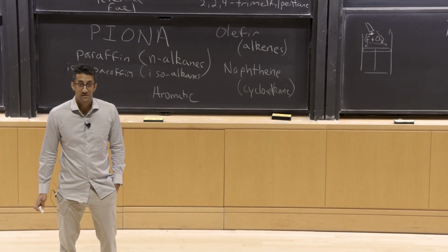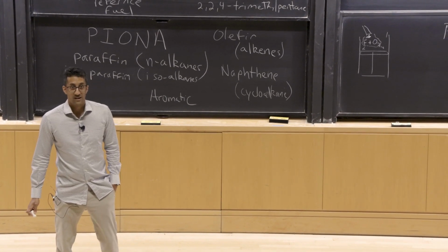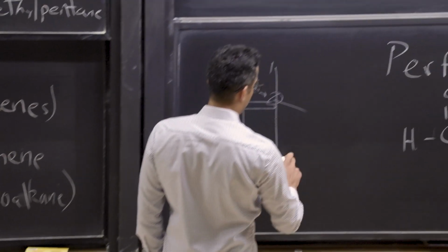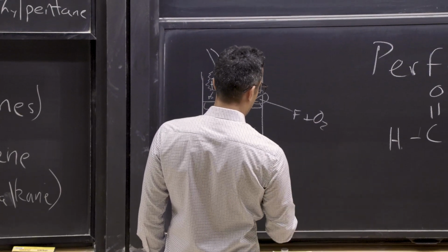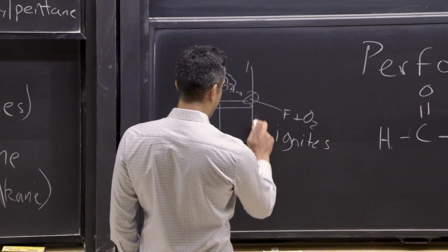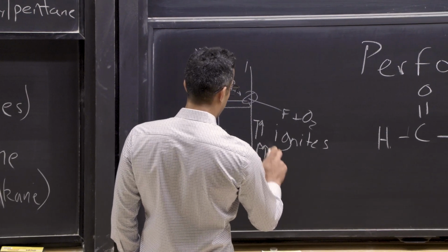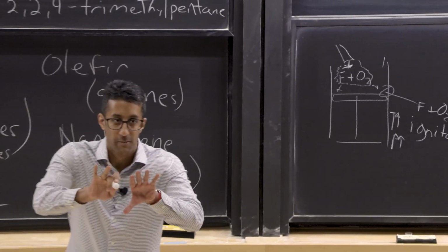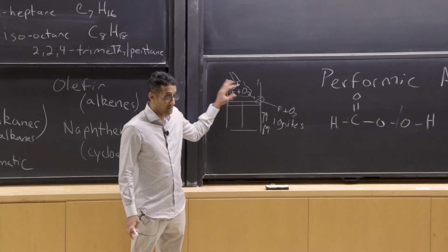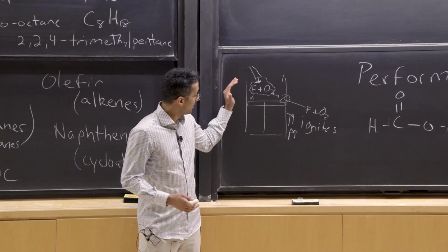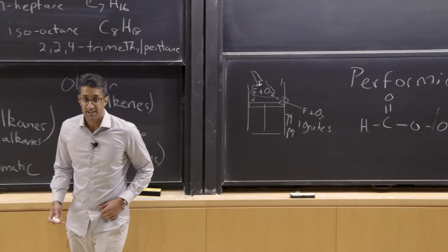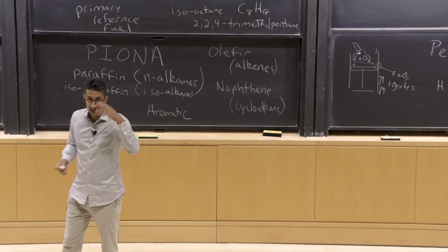Where does the autoignition happen in knock? In the end gas. It's called end-gas autoignition. The end gas is here, and this mixture ignites. Why does it ignite? Because temperature and pressure are rising in this end gas. As the flame is pushing it, it's compressing that end gas. That end gas was cold when the spark fired. It could not react, but as this flame keeps pushing it, it's like a compression ignition. And that end gas auto-ignites, and you get knock, and that's bad for the engine.